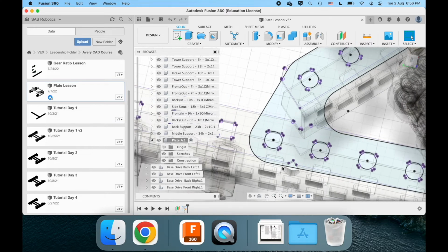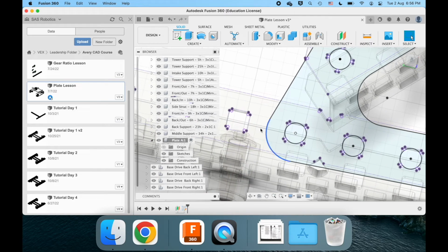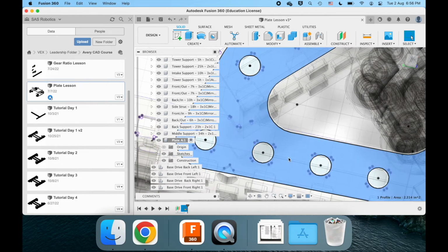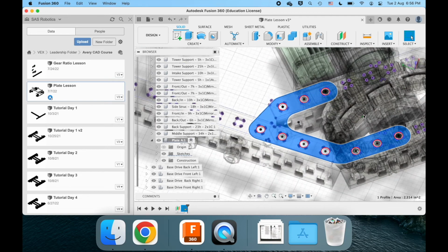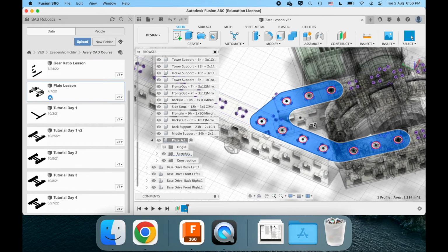When you project surfaces, unless you want those lines to be solid, you probably want to put them in sketch mode. Just an important thing to keep in mind. So I'm stressing that. Okay, but because we did everything properly, this is a nice, easy surface to just click on in one swoop.